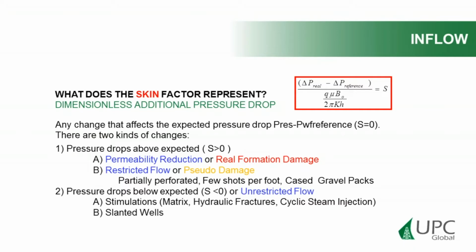The reference is going to be no damage, open hole, smooth condition. So when the drawdown is exactly the same as expected, the skin is equal to 0.